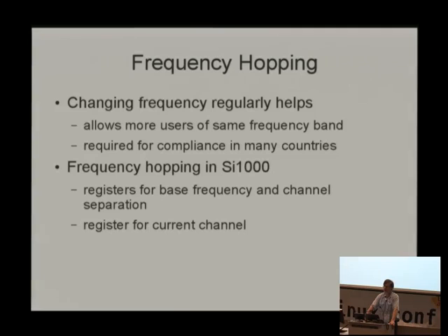The regulators like radios to have low interference potential, as it's called. You know, there's the LIPD rules in Australia, the low interference potential devices, which are devices that are unlikely to interfere with each other. And if you don't want to get a special license or a ham license, you just want to use the class licenses that are available to everyone, then you have to follow these rules, which specify things like maximum time you can spend on any frequency and minimum number of channels that you operate over and the width of each of those channels, etc.